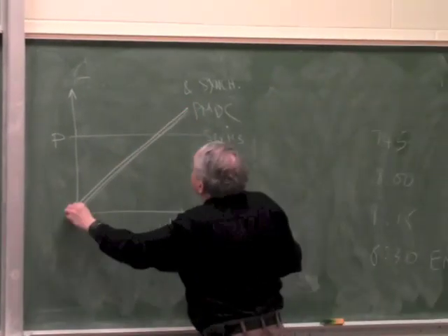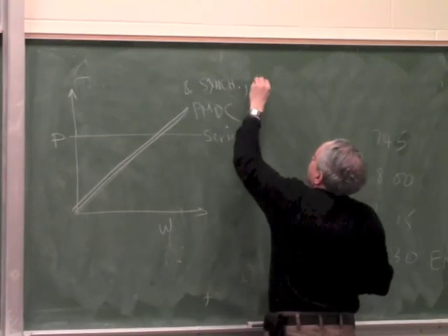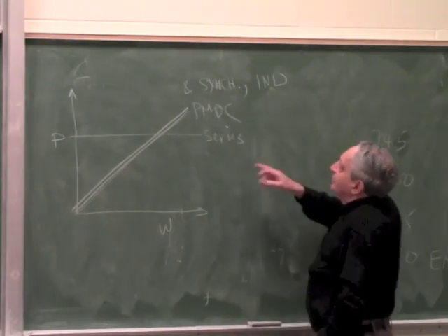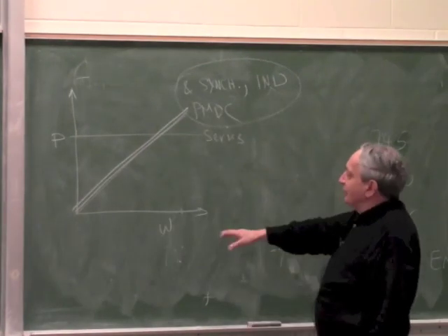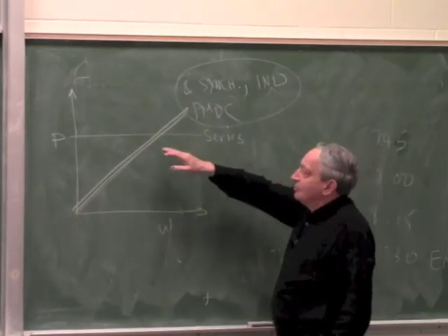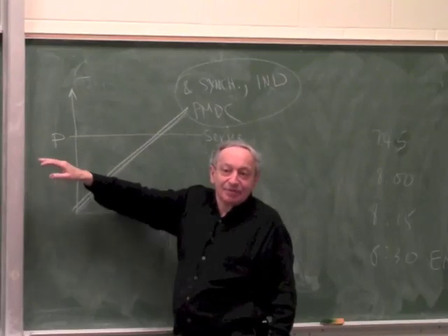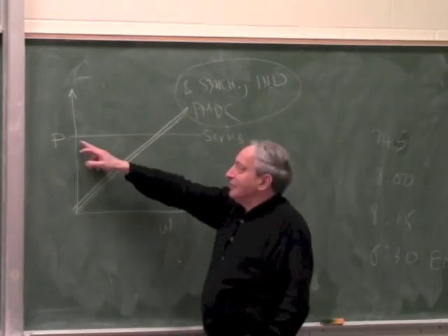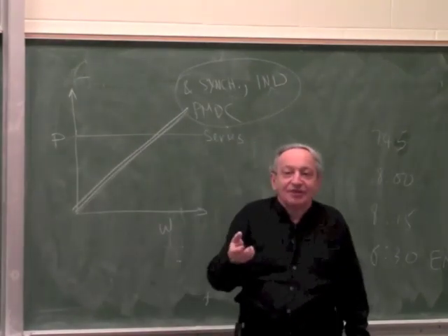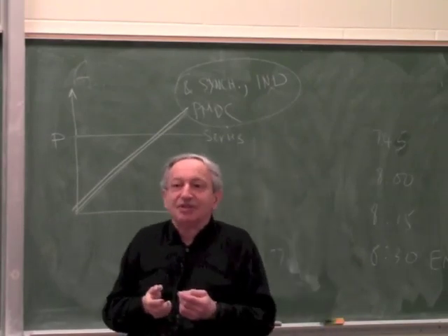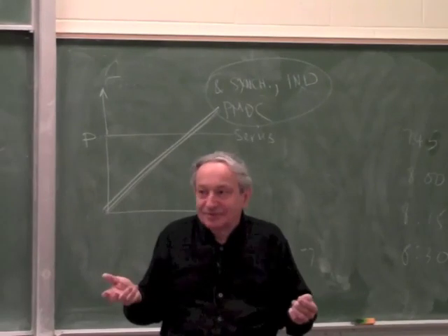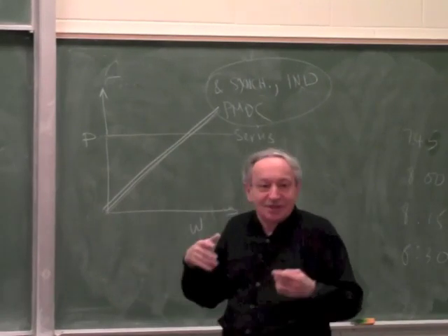Basically, hysteresis, induction, and PMDC: all of these look the same if you draw power versus omega, except a series motor, which is constant power, which is very desirable. Because remember, constant power means a huge starting torque. Because constant power at 0 frequency means infinite torque. So that's why this series motor is such a nice motor.